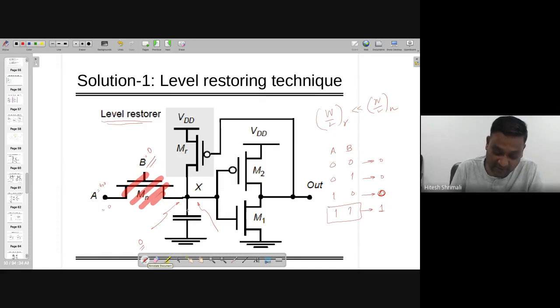It's an open circuit, and whatever voltage was here, held at the positive plate of the capacitor, will remain there. It will not go anywhere, right? There is no discharge path, right? I don't see any discharge path because the input of this one is infinite, the input of this one is infinite. Looking at this drain, that is also R0, so that is also infinite, or you can say a bigger value. So there is no path where this whole capacitor charge goes to 0. So in that case, it remains at the value where it was.